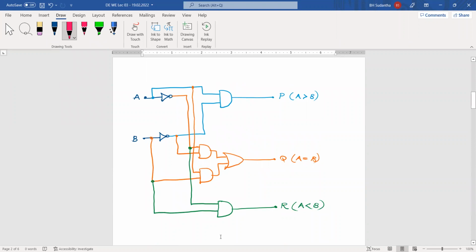I think at the moment we have tried many types of problems. If you are okay with all these steps, when you consider the basic designing procedure, we have to identify the inputs and outputs. That is the first step. The second one, you have to prepare the truth table. When you prepare the truth table, it means that you have done 50% of your problem. The third one, you have to write output Boolean equations.